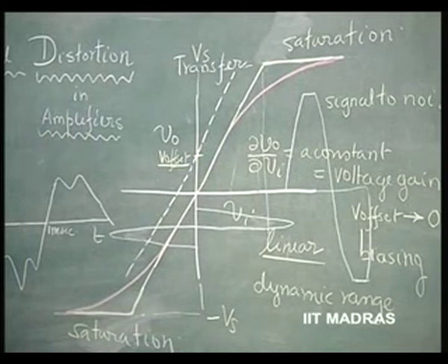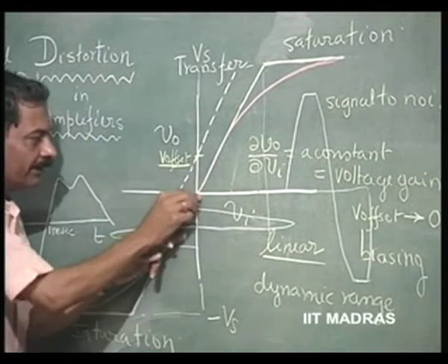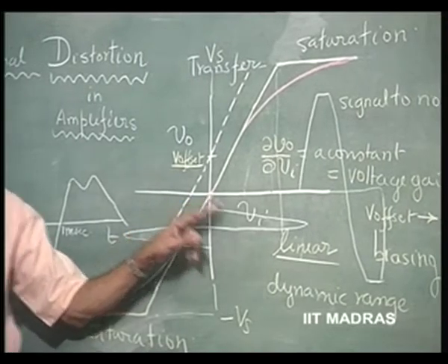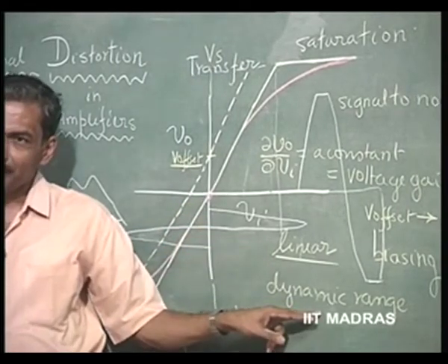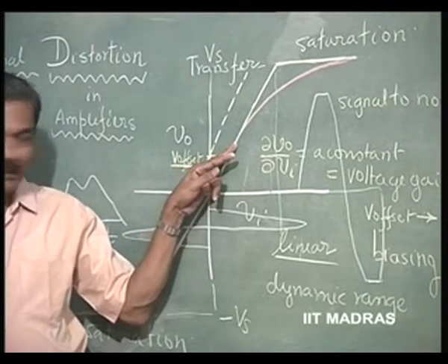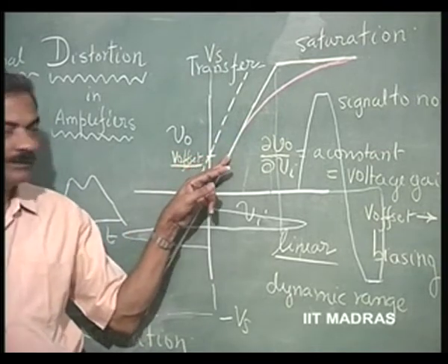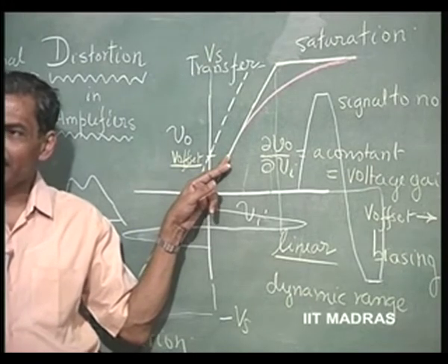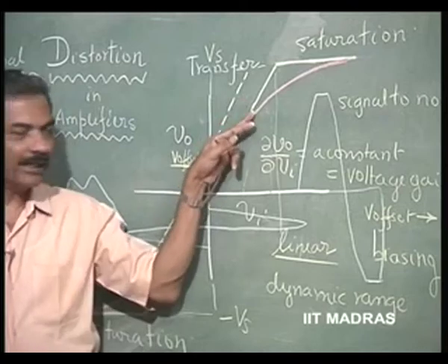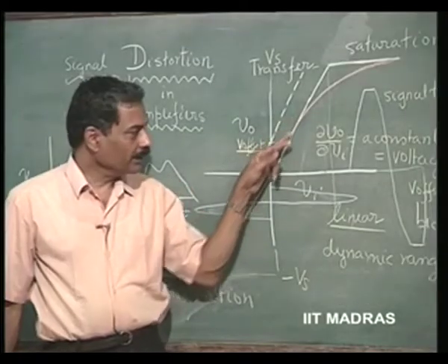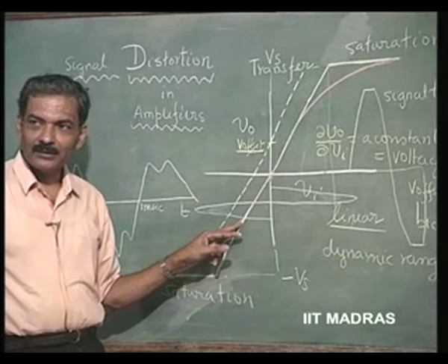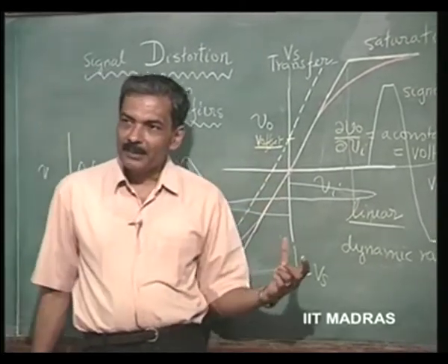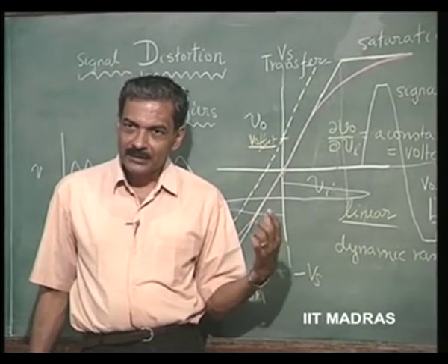that causes us to fix the operating point very carefully at the middle here in this case, so that the dynamic range is maximum. Operating point, because of offset, can shift to this, even then it is amplifying, but the dynamic range gets curtailed. Here on this side it can go only up to this point, on the other side it can go this much. Similarly, if the offset is here, then again the range, dynamic range of the amplifier gets curtailed.